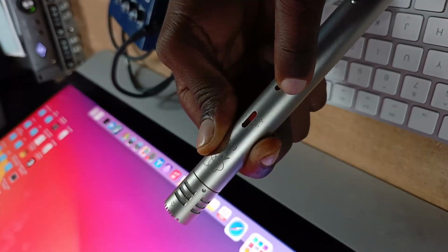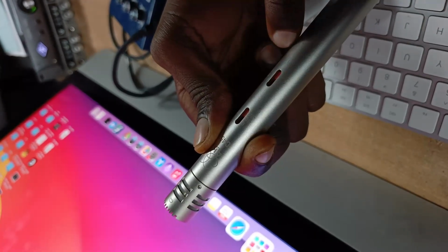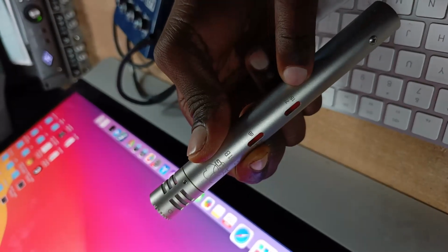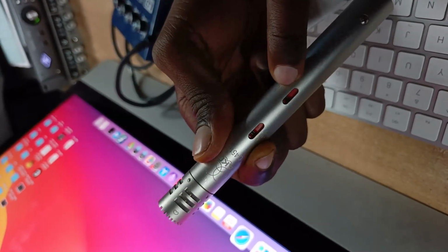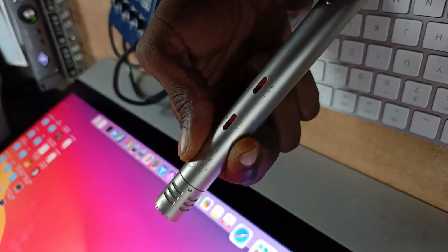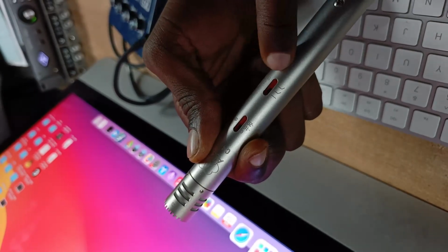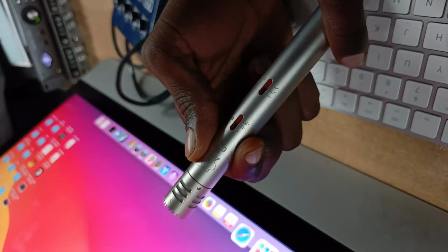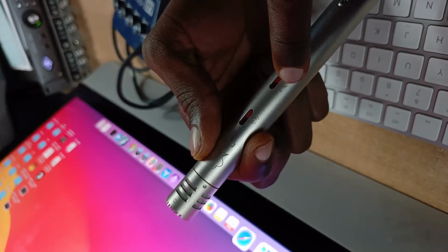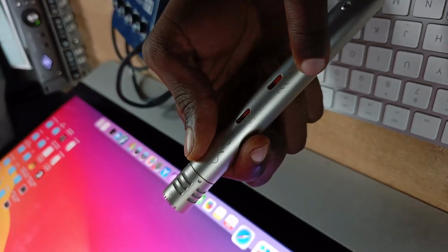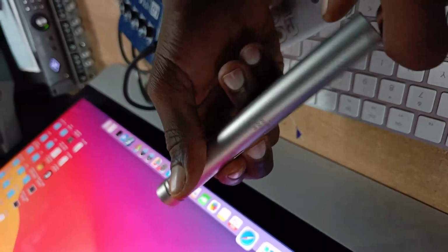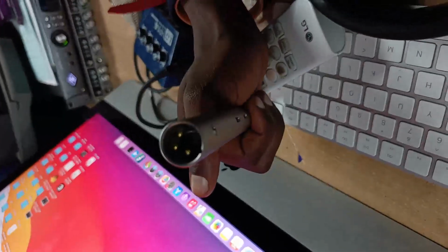There's a band pass filter, a low cut filter, and the amount of frequency you're going to cut off here: 75 Hz, 150 Hz low cut. Which means everything under 150 Hz is being cut off. And here it means everything under 75 Hz is being cut off. And this means line signal. Everything is coming in. This is the output.